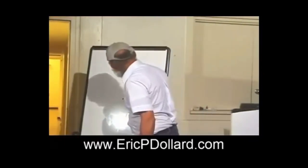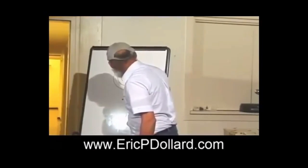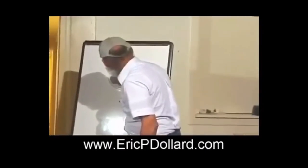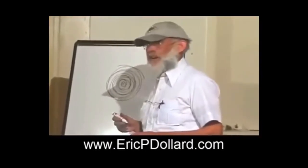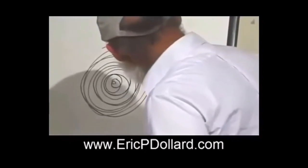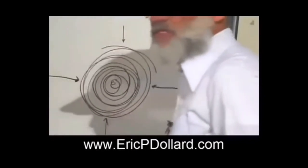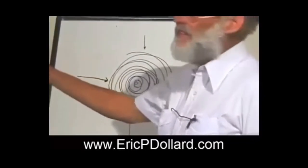was it had a pair of coils, 90 turns, and 1 mile of wire on the ceiling of the first floor. One went one way in copper, and the other one went the other way in iron. 10 gauge copper, 14 gauge iron, soft iron wire, all insulated. And there were 4 spark gaps that were remote controllable by compressed air and plastic pipes, so you couldn't have any metal in there to short this thing out. The whole thing was charged up with 100,000 volts from the thing that spins on the outside.